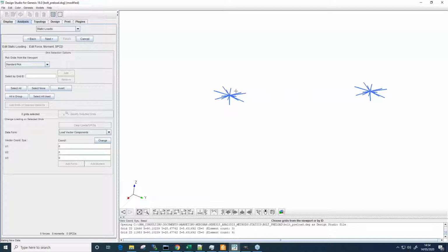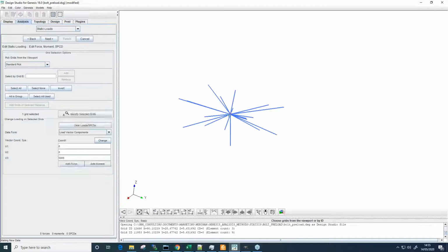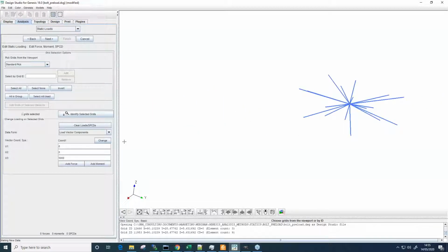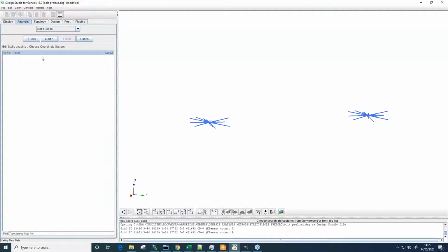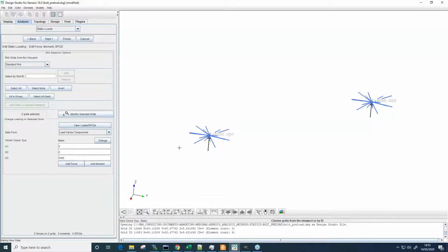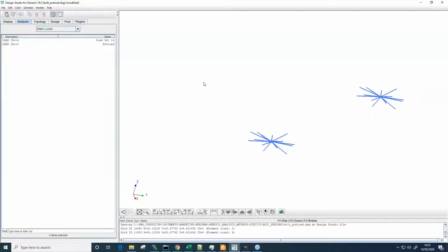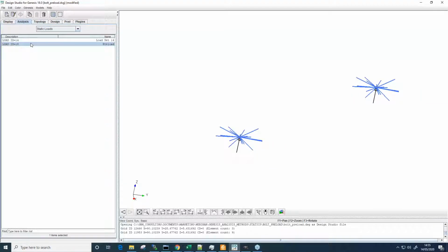Now, bearing in mind that we've given it that convention that I chose to call those elements bottom when I made the selection. So bottom to top in this case is going up the positive Z direction. So if I want to put 5 kilonewtons of preload, I can apply that to these center nodes, like so. I almost tricked myself up there with a little coordinate system. Good. So now they're applied. You can see they're in place.